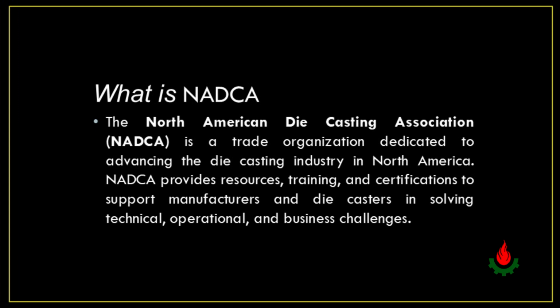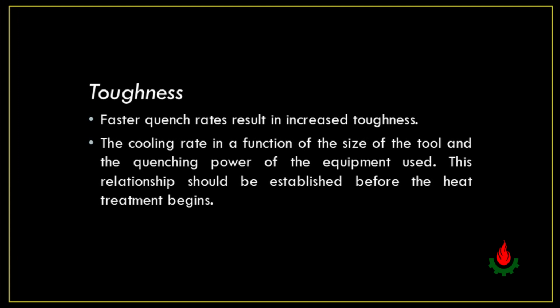Toughness. Faster quench rates result in increased toughness. The cooling rate is a function of the size of the tool and the quenching power of the equipment used. This relationship should be established before the heat treatment begins.